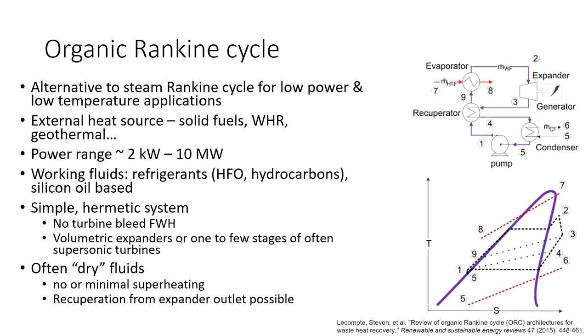Very often the working fluids are so-called dry. We can see that here on the right hand side figure, where we have the saturated liquid curve, which looks quite normally, but then from the critical point, when we have a look at the right hand side of the vapor dome, at the saturated vapor curve, we can see that it actually goes slightly backwards.